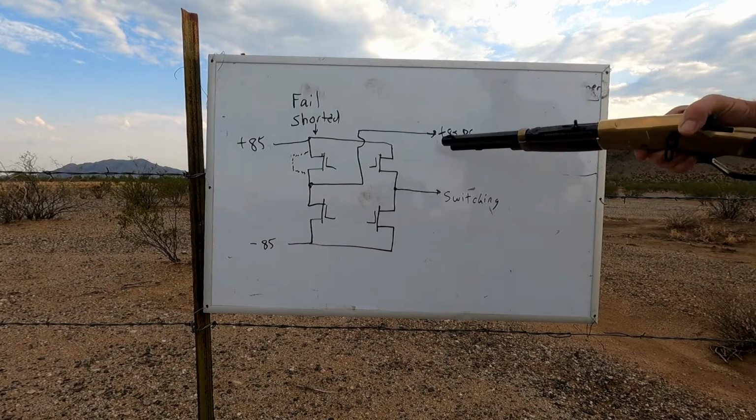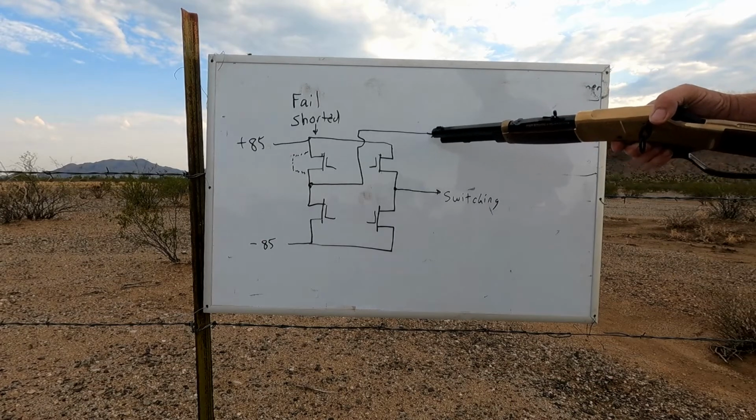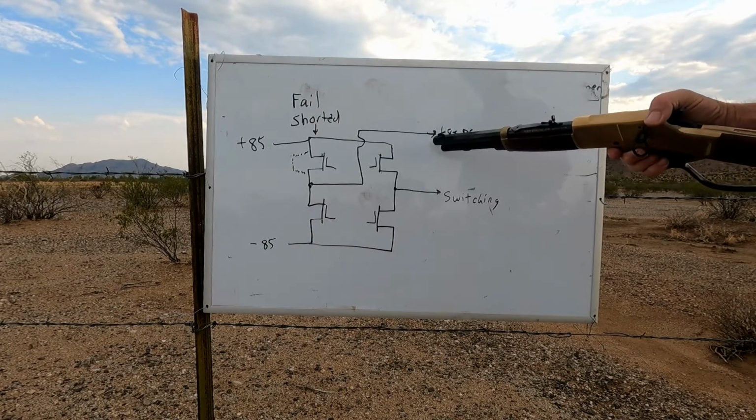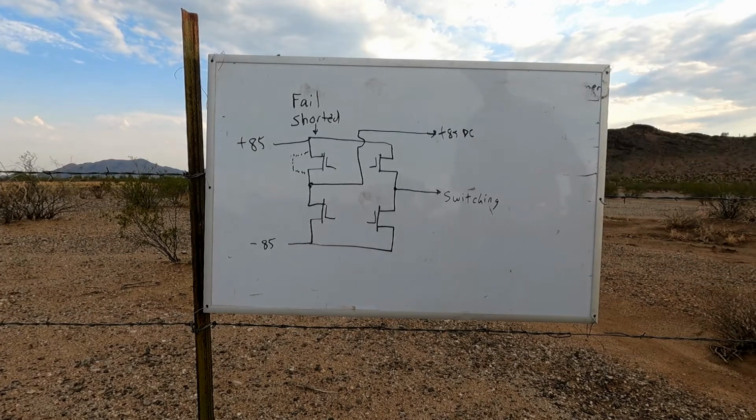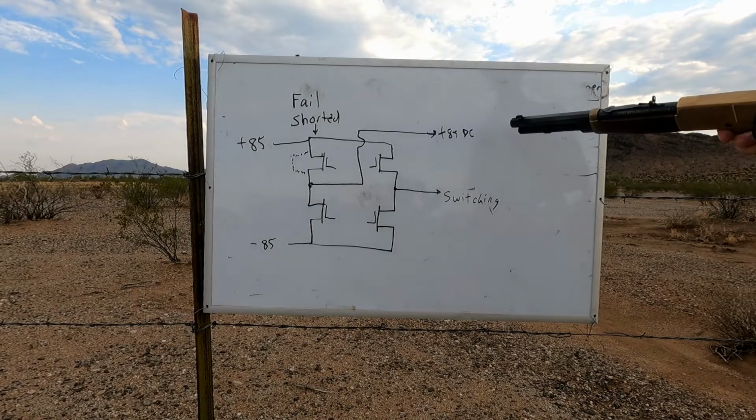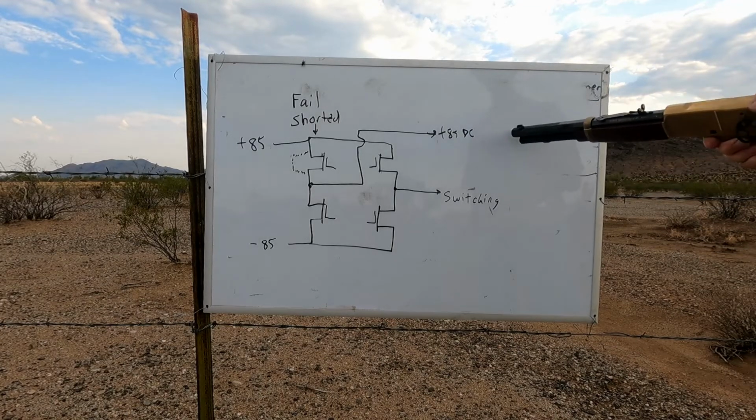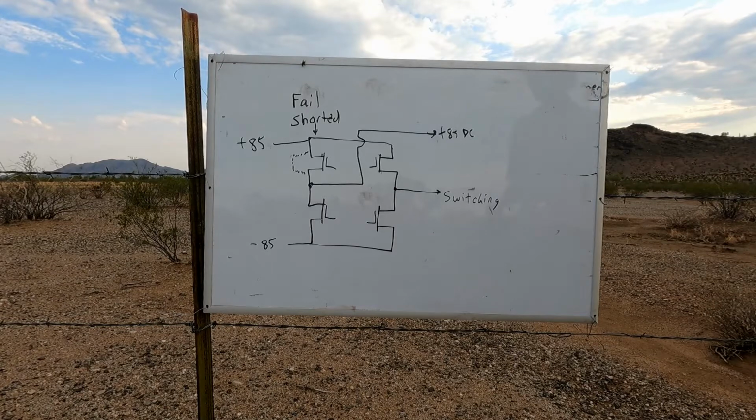And of course, the inverters are not built with circuitry to specifically detect this type of failure. And if it detects the failure, there's only one viable solution, and that's to incorporate a mechanical type of relay to open that circuit. You can't save a semiconductor device with a semiconductor device. So we're going to explore this problem a little bit more as we progress here.